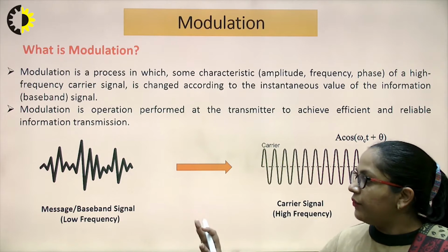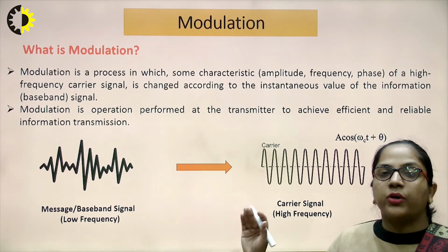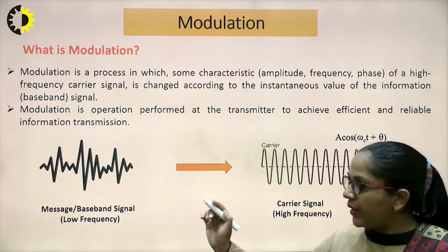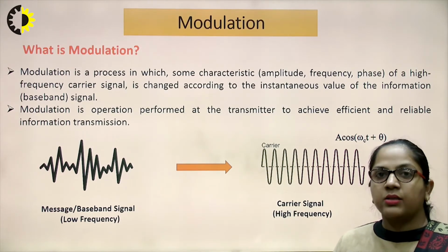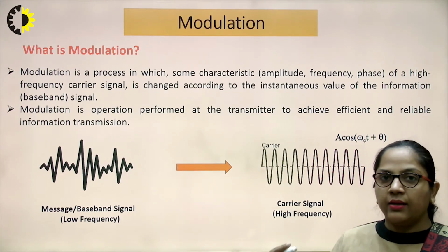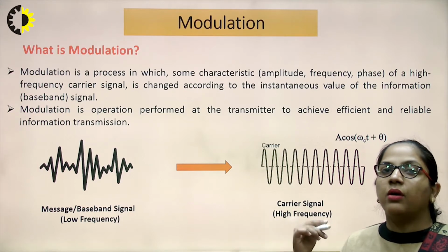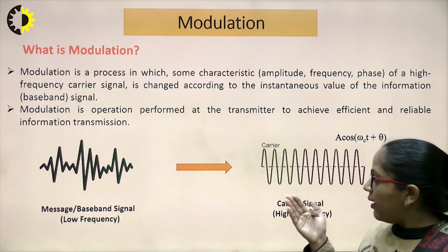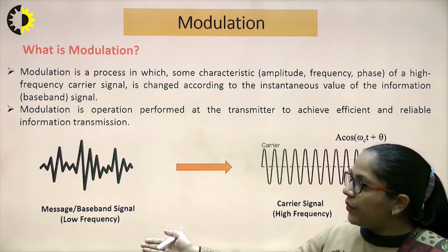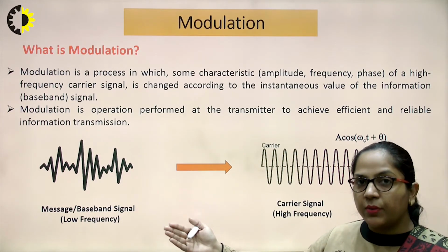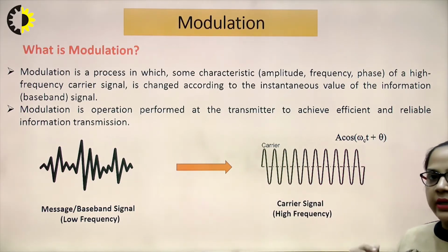But before that, we need to understand what modulation actually is. So we have a low frequency signal that is not suitable to directly transmit over long distances. So we need a high frequency periodic waveform that will carry this low frequency message or information signal to a far away distance.